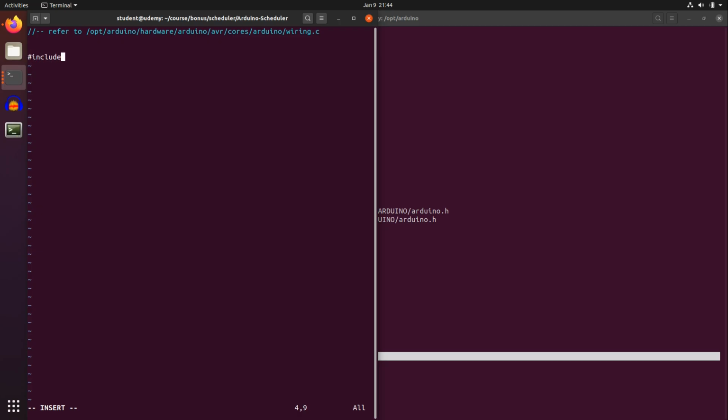I'm going to have a delay.h for the function definitions. I'm going to have, let's say, a start timer. Don't interrupt in case the timer is in power reduction mode. Wake it up, we need it.